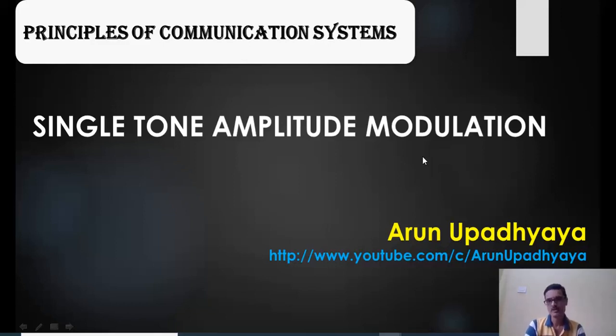In the last video, if you observed, I considered the entire spectrum of an audio band, and after modulation, how this low pass signal is translated into a band pass signal occupying a certain bandwidth. Where I considered the entire audio band of say 0 to W Hz, the highest frequency assumed as W Hz. But in this video, I'm going to explain considering a single frequency in the message spectrum. That single frequency is fm Hertz. Let us consider that fm can be say 1 kilohertz, 5 kilohertz, within the range of the audio band of 20 hertz to 20 kilohertz.